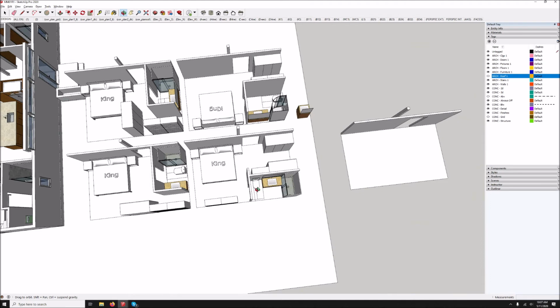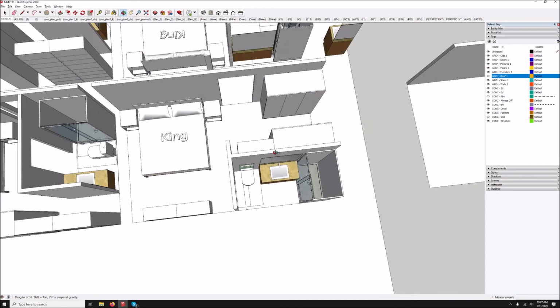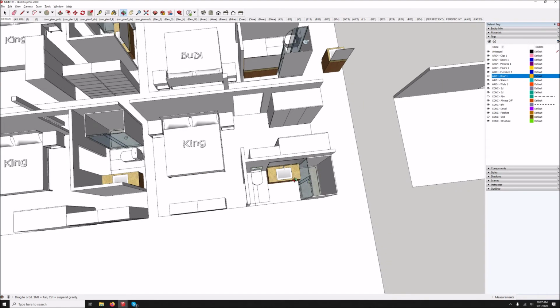Anyway, the key takeaways here are in a tight space like this, inches do matter, and it's a question of priorities, give and take, where your priorities lie. I made this work better by virtue of making the sink just a little bit smaller. I'm at the limit as far as the space allowed by code for the toilet already. That's 30 inches.